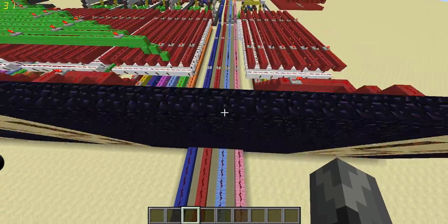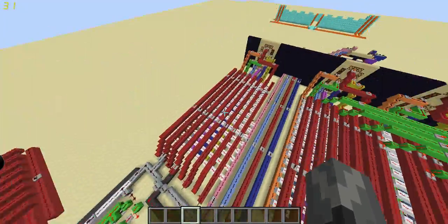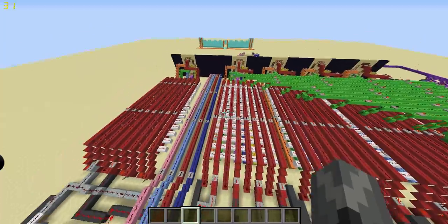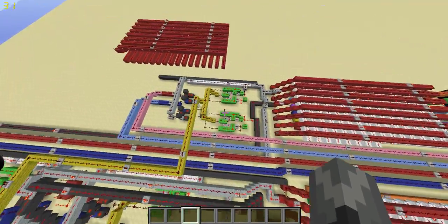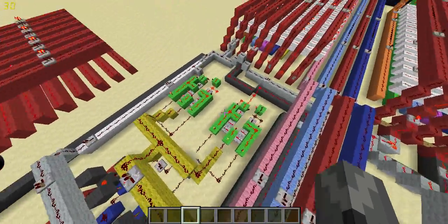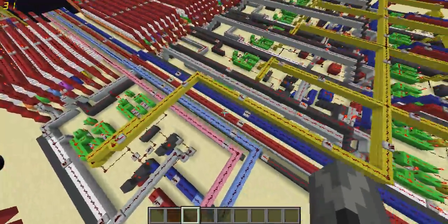these are the 4 input lines that go into the actual circuit. Everything in red back here is the controls for each of the hex displays. This right here is my increment decrement counter. The yellow line is the clock. The green is the JK flip-flops. So that's my increment decrement counter in 2 bytes.